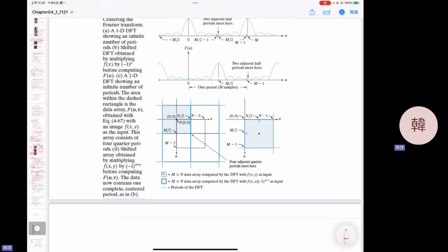So that's the same way. If you transform to the frequency domain, but I only use a point notch function, only one point will be removed. The DC value will be removed. What's the result? The result is just like this one. So you can compare the original image and this one. This one has no average value, no DC value there. The DC of the original is nonzero, while the DC of this new image becomes 0, because every point has the average subtracted. So the DC term is removed, and the result is like this one.